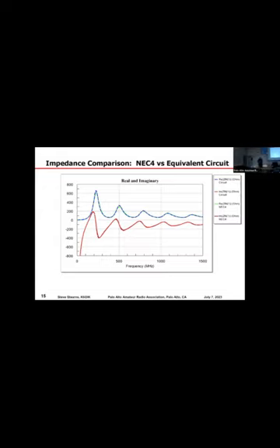There's a dashed curve and a solid curve overlaid on the top and on the bottom. One is resistance, the one on the bottom is the reactance, and they track very well. So it shows that you can construct equivalent circuits that match the impedance on the Smith chart extremely accurately if you use the right circuit topology, which means all the right elements connected the right way and the correct values for all those elements. Okay, let's see the next chart.